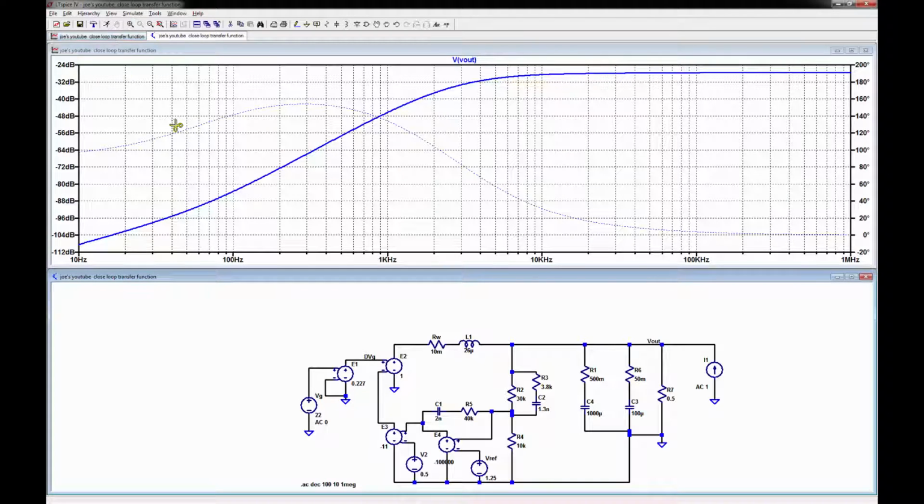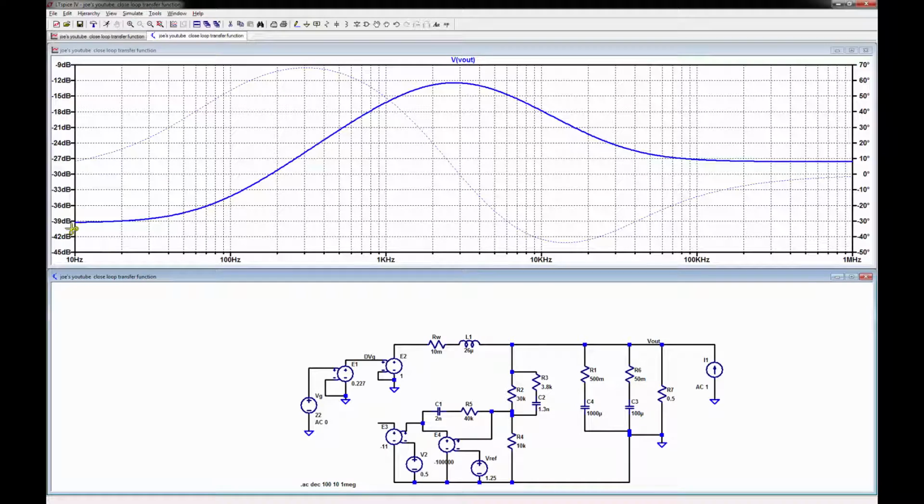So let's go ahead and do our little clip. We cut that. And now what? We're measuring open loop. But let's attach this to here. And now when we go, there's no loop. There's no loop to modify this. So you're going to see us here. So let's run it. Let's see if I'm telling the truth. There it is. Minus 29 dB. It's coming up, and it comes back down in here.